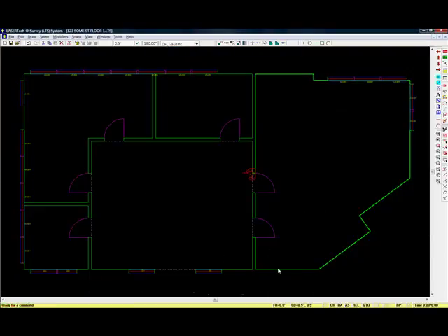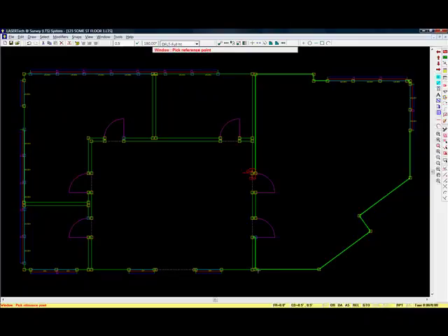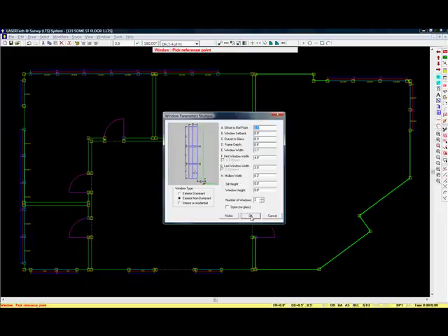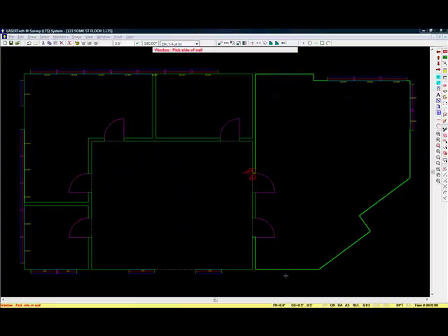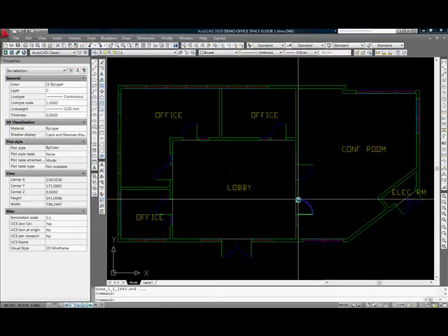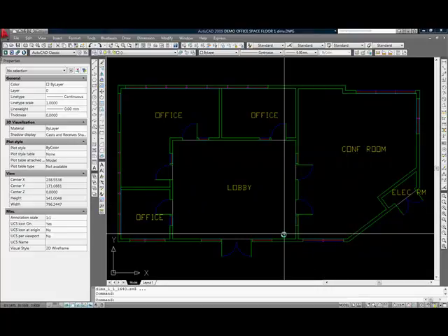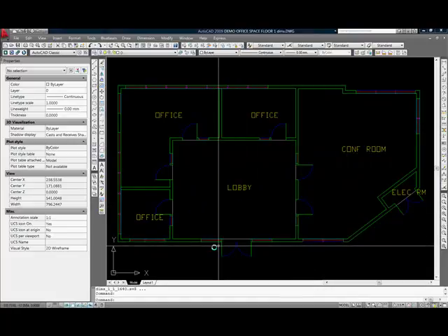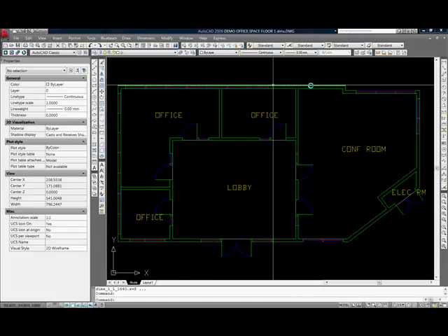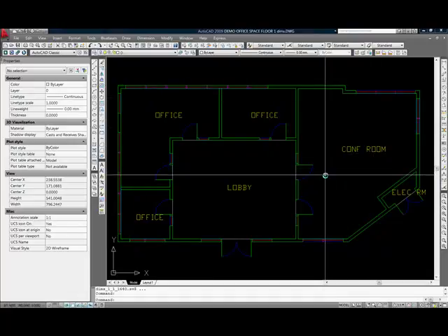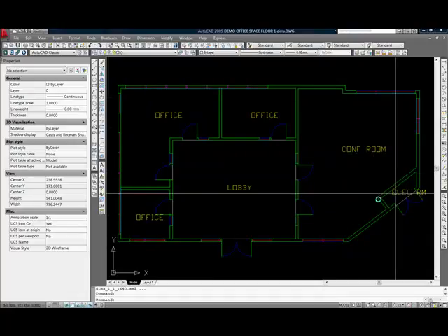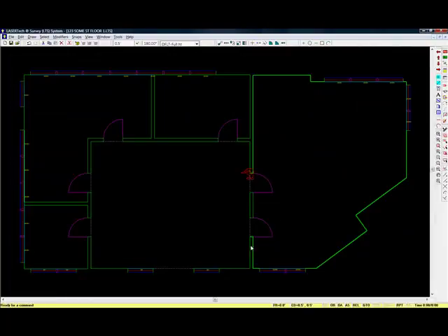And then we also have a couple down on this wall. So we measure up from that corner. Again, let's say it's 1 foot. Otherwise, everything's the same. And there you go. So we go back to AutoCAD, and you can see we have pretty much everything except for this electrical room. Now at this point, what we want to do is do a chain around the perimeter. We always do that if possible, and we're going to need that in order to lay out this electrical room.